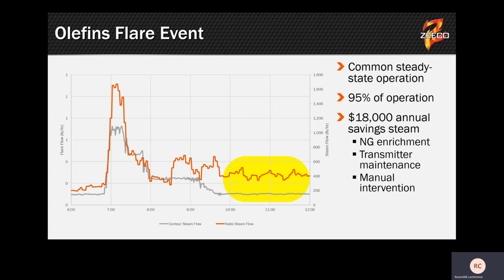And this doesn't include other incursions. And this is only a measurement of the steam savings. There's many, many other residual savings. If this is a facility that has to comply to combustion zone net heating value, there's a possibility that for every pound of steam that they're injecting, they need 1/3 pound of fuel gas enrichment in order to achieve the proper NHVcz. So there's potentially quite a bit of savings in fuel gas enrichment, as well as the longevity of the equipment and other impacts.